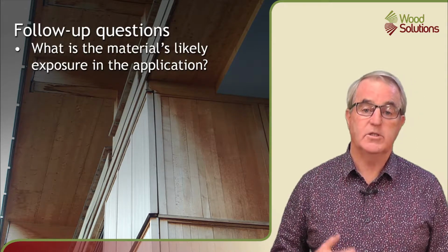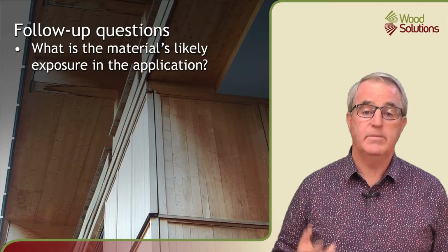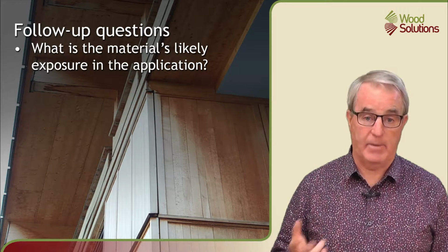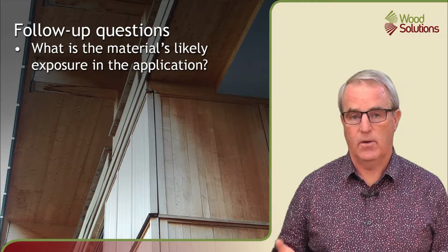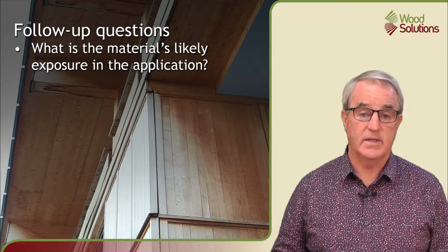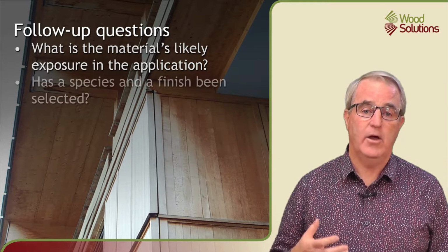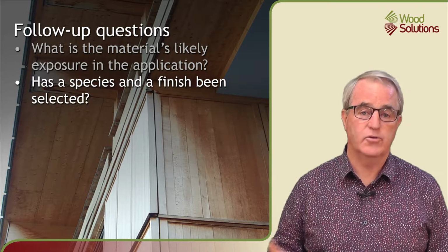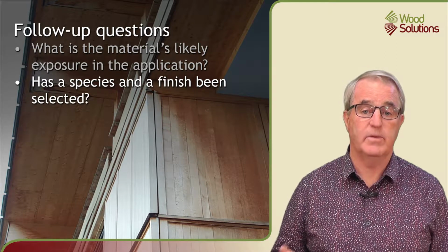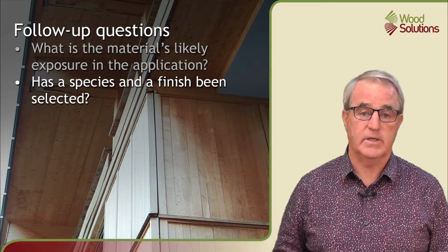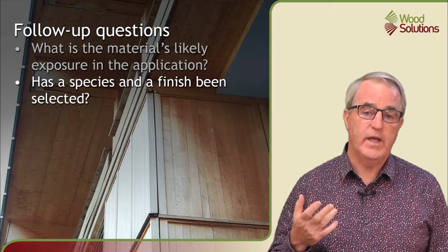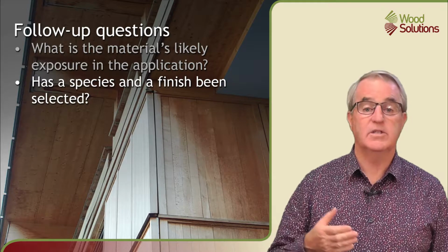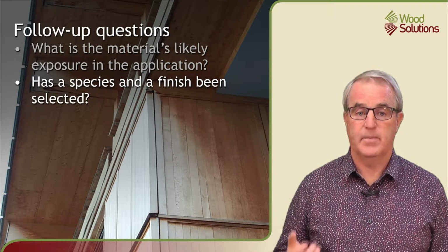The follow-up questions to ask include, what is the material's likely exposure in the application? Is it in a deck or a walling? Does it face the sun? Next, has the client picked a species and a finish? If they have, is the natural durability or level of preservative treatment of the selected timber adequate for the task? Will the finish improve the timber's performance or just increase maintenance overall?